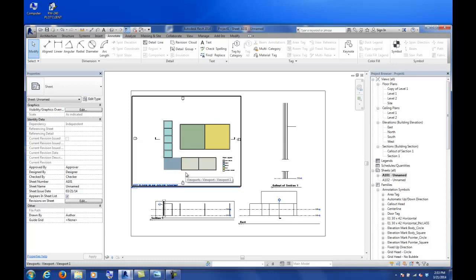But once you have all of this on a piece of paper, what we can do now is print it. So you're ready to print it, send it over to the print lab. The best way to print out of Revit is to print to Adobe PDF. That's why I'm glad they finally got that on these computers. From Adobe PDF you can send it to wherever you need it to be plotted. So that's really the best way. You'll generally get good line weights when you do that versus going straight to a plotter.